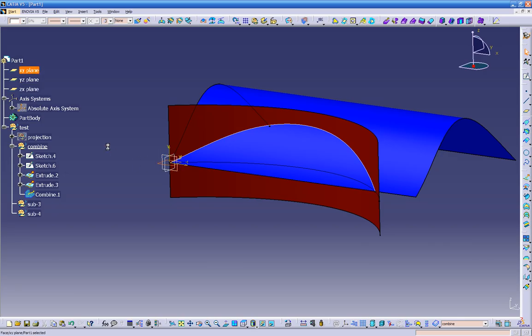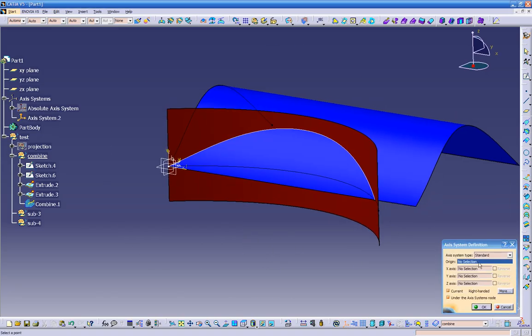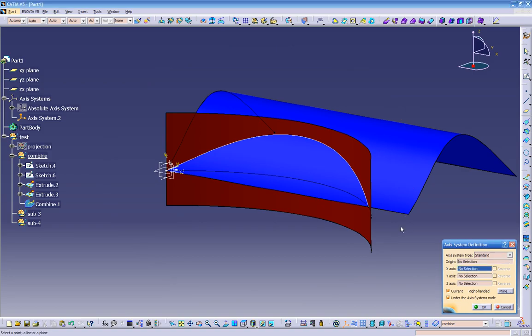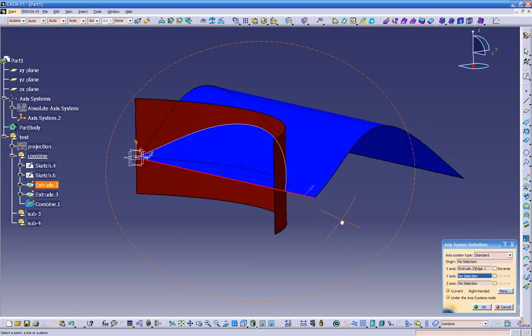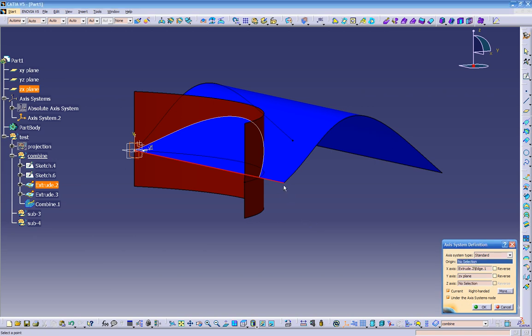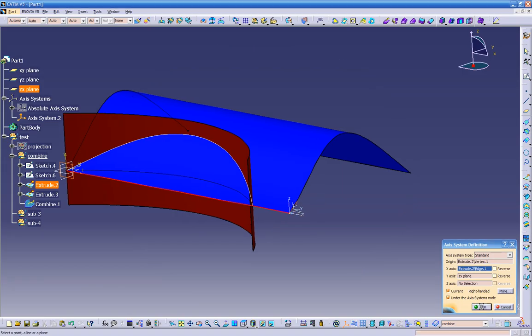and whatever. And what we can do, instead of creating the axis ourselves, because you can create your axis on your own, you just click an axis system, and automatically by default it jumps into the origin. But you can create your own axis, so you get your X over here, and then you get your Y over here. Then you say you want it over here at this point. So you get your own axis, and you click OK.